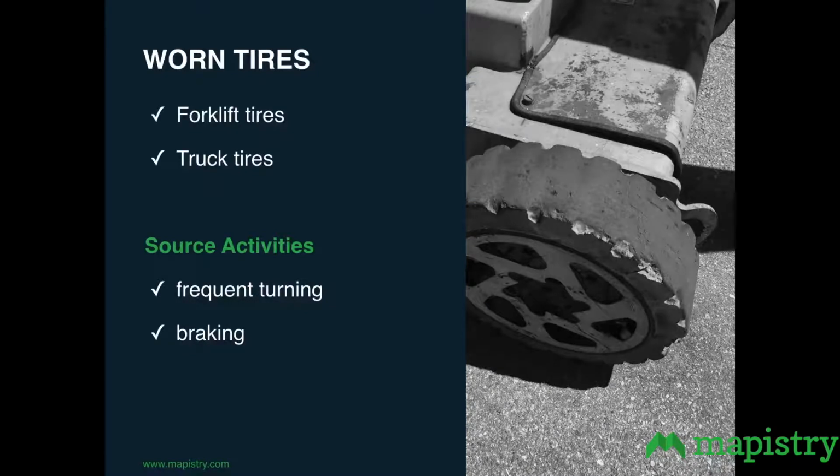That little rubber particle has mass to it. If it's winding up on the surface, it needs to be treated just like dirt, sediment, sand, because it can show up in the TSS samples and potentially cause you to exceed benchmarks or action levels, etc.